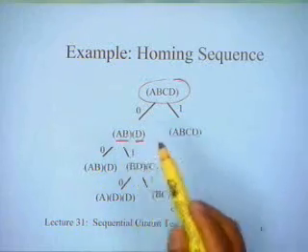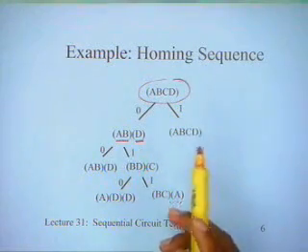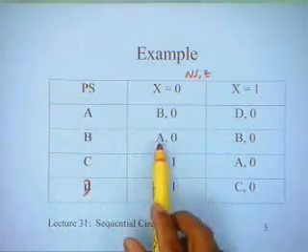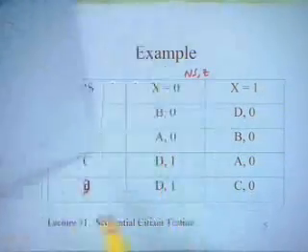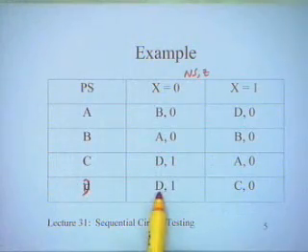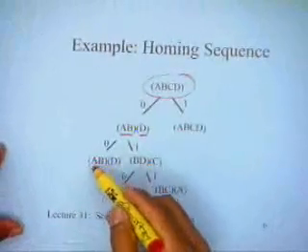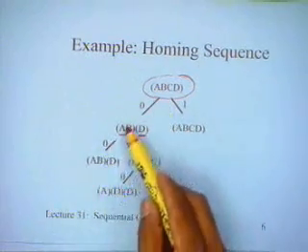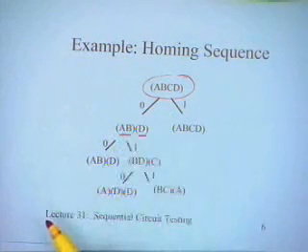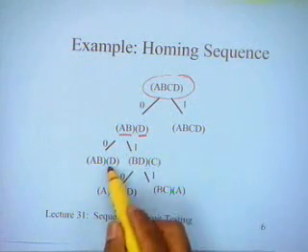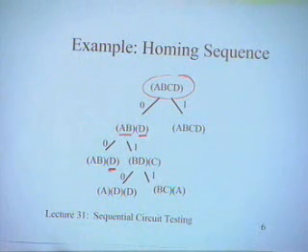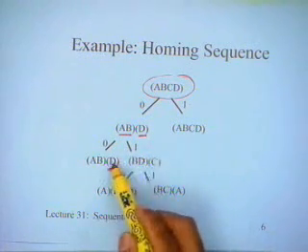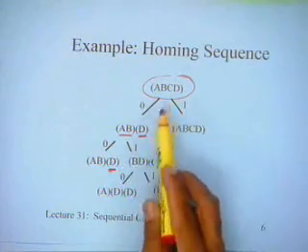Now I can again either apply 0 or 1. If I apply 0, I reach the final state of AB; AB will remain AB, and D will remain D, and within AB I will not be able to distinguish, so this uncertainty vector is ABD. And this is a terminal node in this tree, because I have not done any refinement over the previous one. This uncertainty vector is the same as this uncertainty vector. These elements are called homogeneous elements or trivial elements. If there is only one element, it is a trivial element. Homogeneous means all the states are the same. So you can write it as DD also, C and D both reach DD.